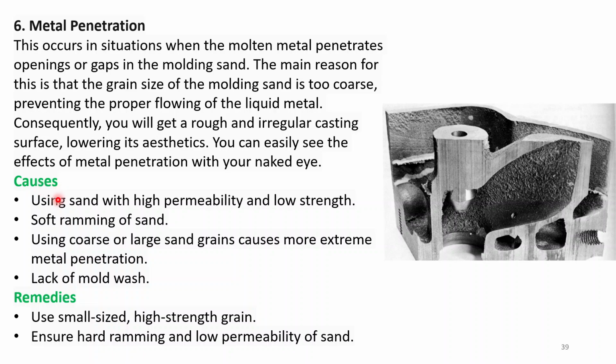The causes are using sand with very high permeability and low strength, soft ramming of sand, and using coarse and large sand grains, which cause more extreme metal penetration, and lack of mold wash. Remedies: use small sized and high strength grains, ensure proper ramming, and also low permeability of sand.